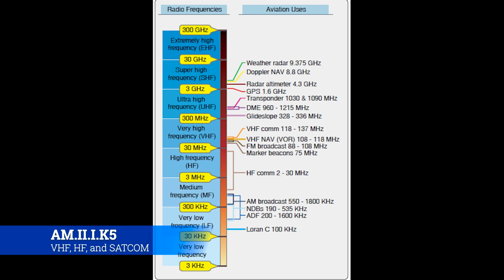Well, radio waves work a lot the same way, where the higher the frequency, the more data points you're going to get inside of one second. That means you're going to have a clear picture, a higher data fidelity of that transmission, but it comes at a cost. High frequency takes a lot of energy, and it can only go so far, so you need more and more energy to go further and further.